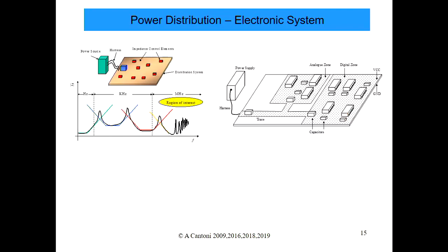But anyway, if we're looking in at one of these ports and seeing what the impedance looks like, then you end up with a lot of these resonances, okay? And later, when you do the project, you'll understand those resonances come from the interaction of the different inductances and capacitors in the actual system, which come from the physical structure of the printed circuit board and the lines and other things as well, okay? And even at high frequencies in the printed circuit board, you also see these really sharp high frequency resonances, and they're due to electromagnetic modes on the actual power planes, okay?